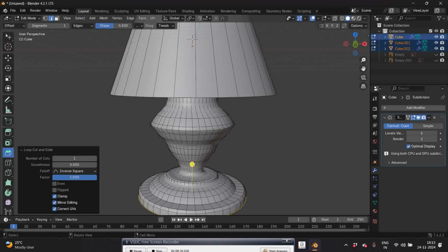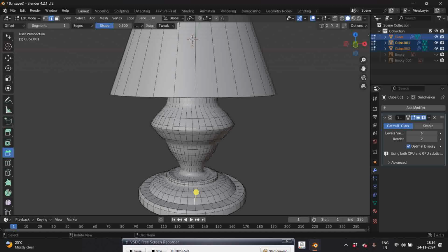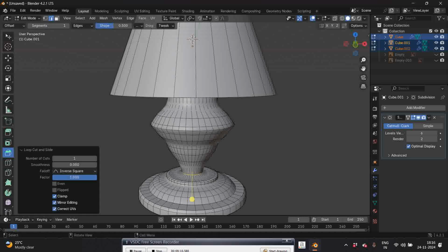Take a mouse basically there where you want to add the loop cut, so Control R, and just slide it because I want it horizontally. So move your mouse slowly here and there, and you will find the circle. So yes, and move it down. Yes, here also. So I'm taking the mouse there and press Control R. Yes, then move it down. Like that you can now sharpen your edges by adding the loop cuts.